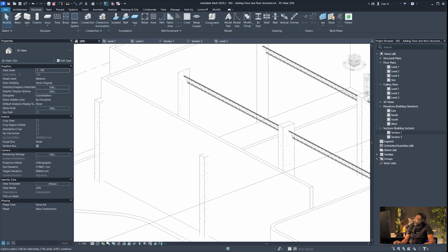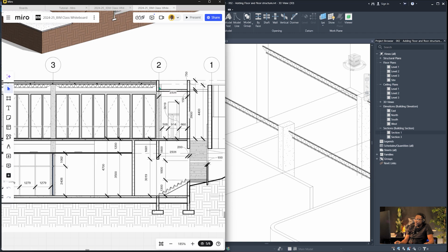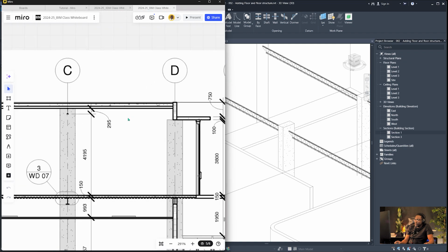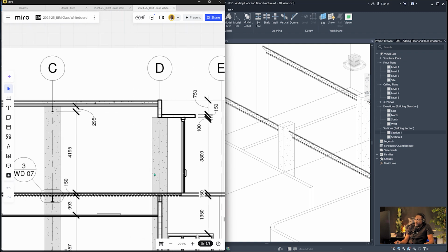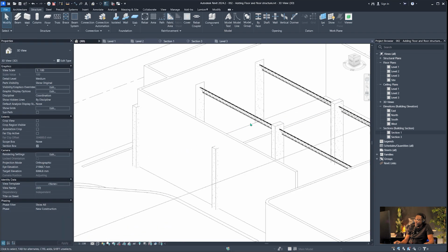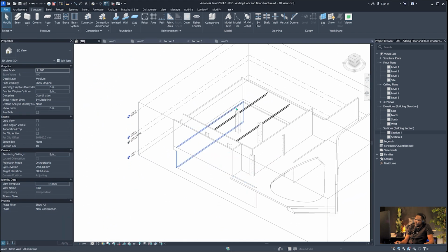Because if we look on our drawings, maybe this one, we can see that it actually stops in, a better one would be this one, right? We can actually see that this column that's here is actually lower. So there is no open web joist at grid line D. There's only at B and C. Oh, and there's another one down here at A. So there should be another grid line and a column actually here, right?